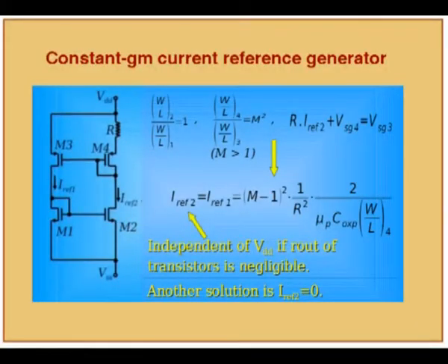Of course, we do some shortcuts, like we provide extra pins. If it doesn't work, at least we apply the current from outside and then let the chip work. But finally we don't want to keep those additional pins. Packaging is very important, size of package, so we don't want to have additional pins. So we put a startup circuit on the chip. So startup injects some current into the circuit.